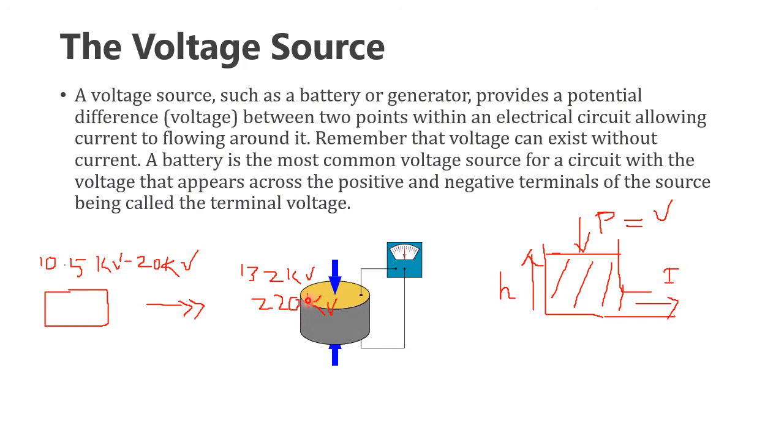Mostly they convert 10.5 kV into 220 kV, or in old transmission lines 132 kV. These are the long distance transmission lines, which feed the receiving station. Again they step down to 33 kV and transmit to the distribution division.